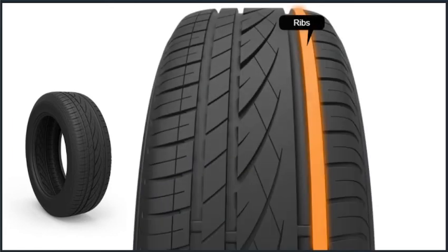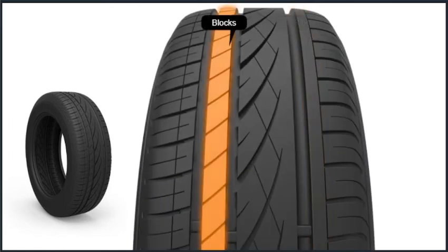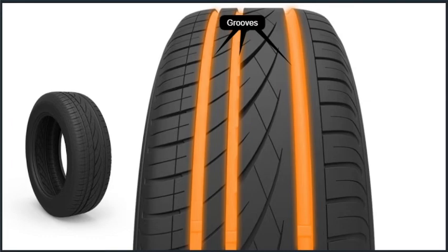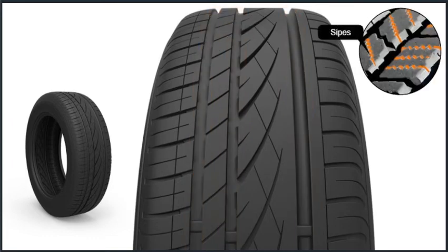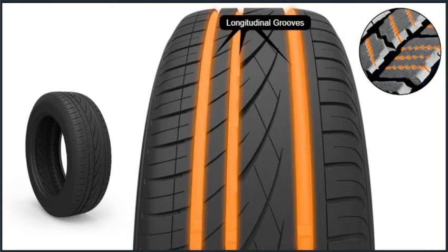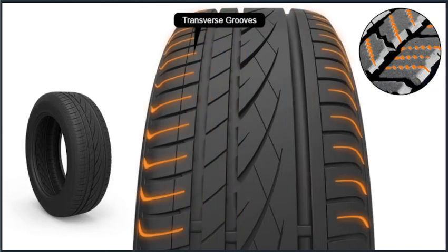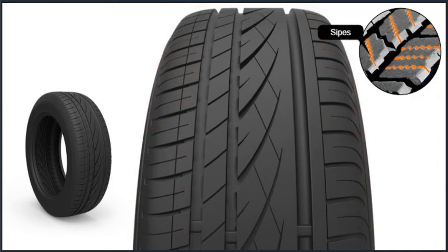Tire tread patterns are the arrangement of continuous ribs, independent tread blocks or lugs, grooves, and thin sipes molded into the tread to fine-tune noise, handling, traction, and wear. Longitudinal grooves channel the water away from the tire and help keep the blocks in contact with the road. Transverse grooves grip mud, snow, and ice, as well as channel these elements away.